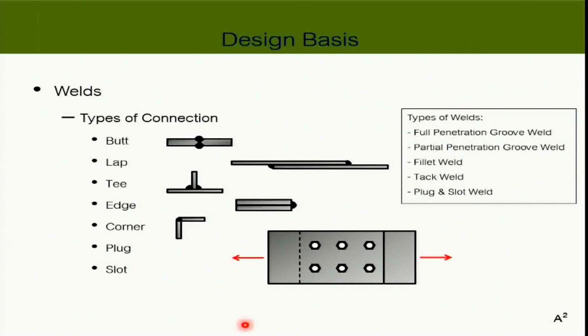Okay, so in terms of the weld itself, we have so many types of weld. If you weld the bottom of the plate together, this is called the butt weld, end-to-end stuff. If you weld it like this, it's a typical weld type that we are familiar with. It's a lap joint. If it's like this, then it's a T. We have the H, we have the corner, and we have the plug and slot. Generally, the most commonly used would be the first three, I suppose.